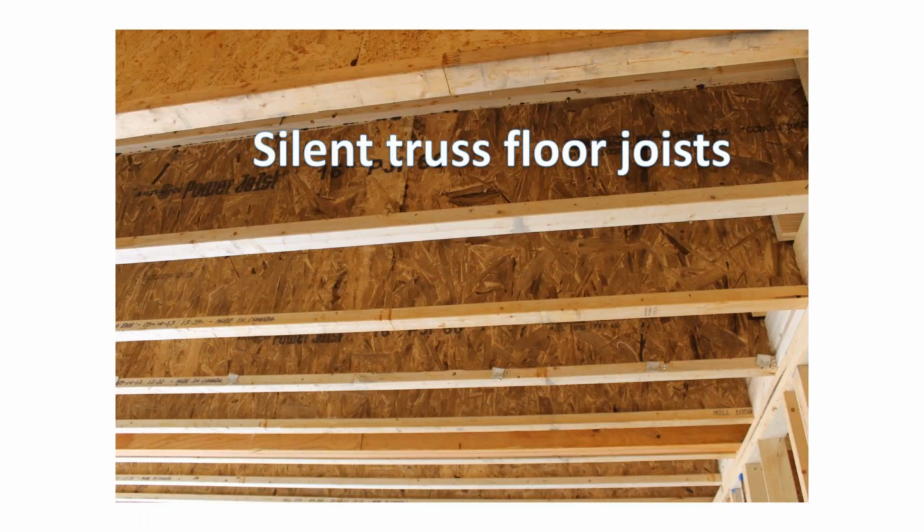They make something called a silent truss floor joist, and that's a picture of what these are. This is a man-made fabricated thing where they've glued chips of wood together, but because it is wood and all of that glue together, it's stronger than a normal floor joist and doesn't require the cross bracing. So if you see something like this, this is called a silent truss floor joist. You can see it when you're in your basement looking up.